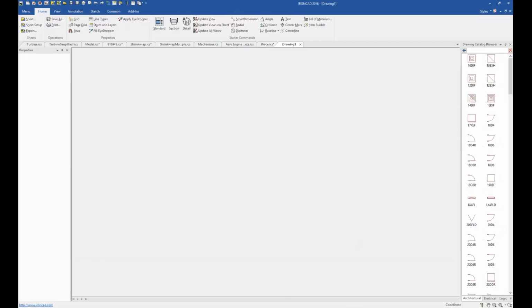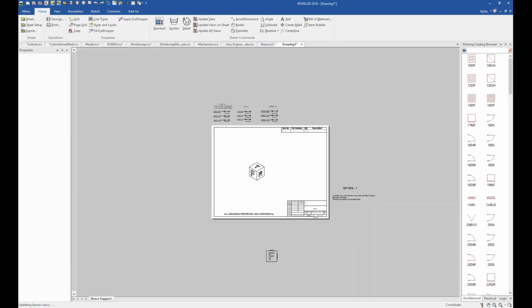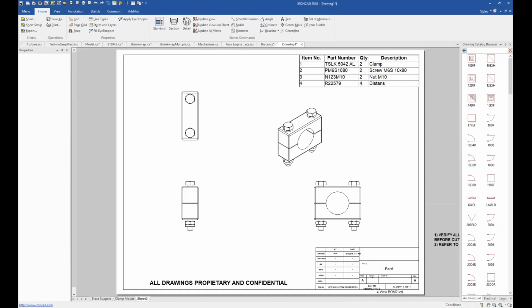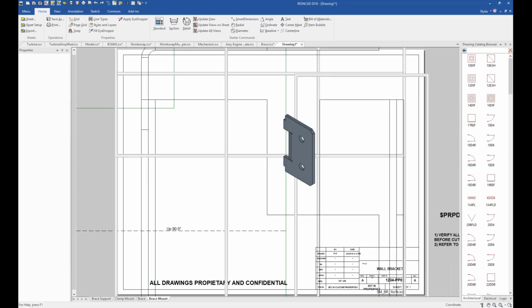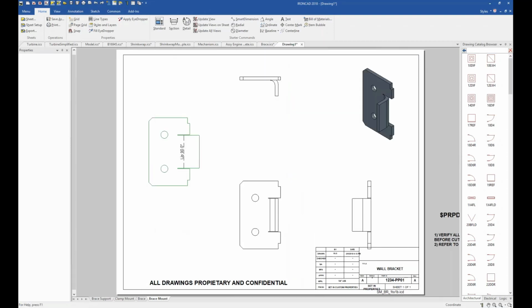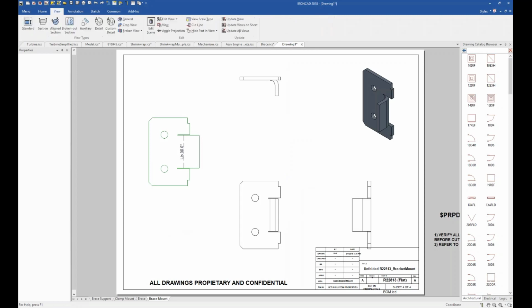And you'll see the process run through here live as it goes through. It's actually going to open up the drawings, create the views for us, update the bill of material, create all of our templates for us. These are creating the updated views for this file. And we are seeing everything updated. So you notice at the end of the result, we see our templates all had text information that automatically pulled from the 3D file, basically the naming information for it. Created our views. This is a 4 view plus an unfolded view inside of the file.